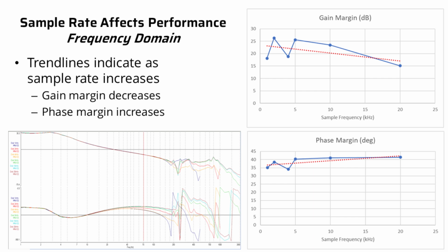And that's to be expected, because when I change the gains proportional to the frequency response, I locate the zeros of the control algorithm, or the control law, exactly in the same space. So I really would expect to have a very similar response. I'm trying to compare apples to apples and not, say, have a higher bandwidth for one frequency than the other. I wanted to compare exactly the same system, but the only thing that we change is the actual sample time or the sample frequency.